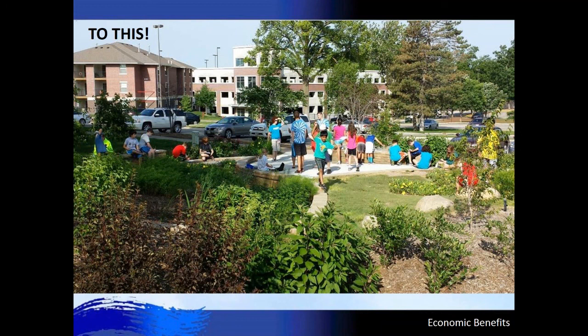One thing you learn over time is that some ideas are not great ideas. Right in the middle of this picture, you see a little lawn area. That was buffalo grass. We put that in, and it struggled for 4 or 5 years. And just recently, it was replaced with a dwarf tall fescue. Sorry, I always get that mixed up. Grass. Which is a very low input grass, but actually is doing better. It's preventing erosion, and it's really better suited. So one great thing about green infrastructure is if you do these projects, go back and look at them each year, and you'll learn a lot of lessons from that.